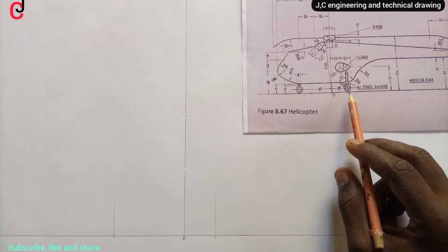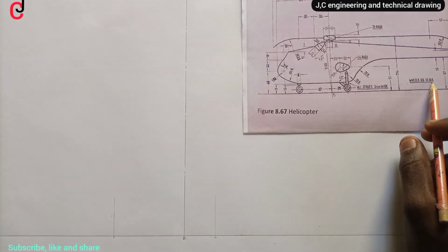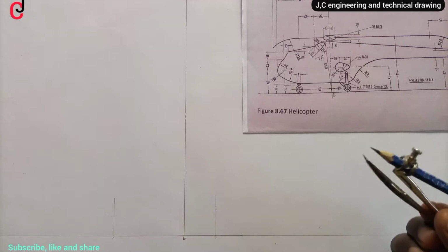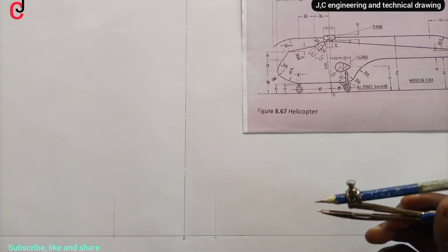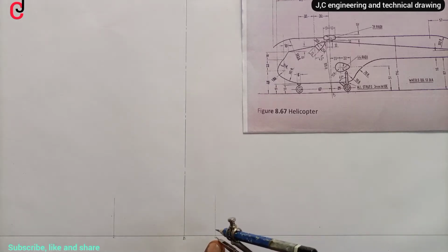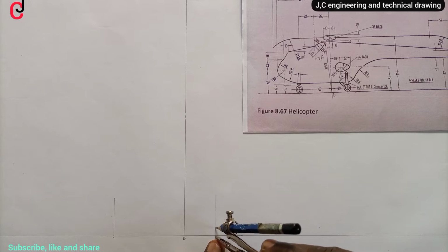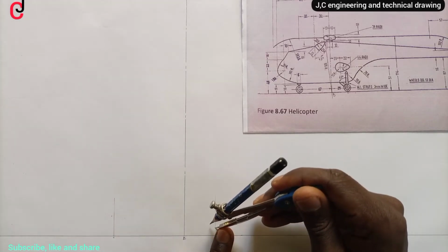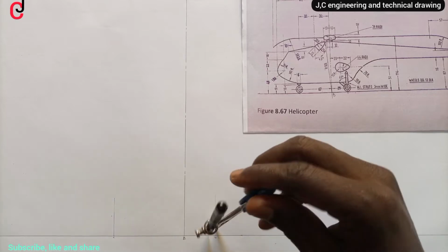Now from our 2 points here, point A and point B, we are told that we have a wheel which diameter is 13 millimeter. So our radius is going to be half of 13, which is going to be 6.5. Taking 6.5 millimeter with our compass, place it at point B, scribe an arc, and then using the points on a vertical line, we'll draw a circle.